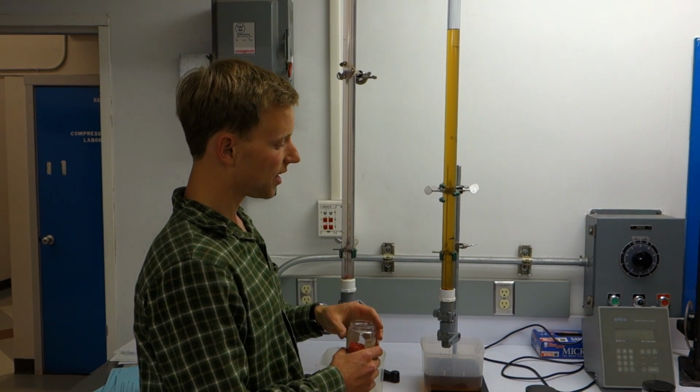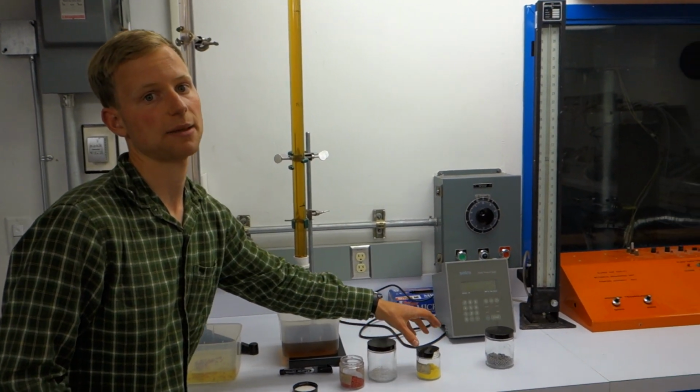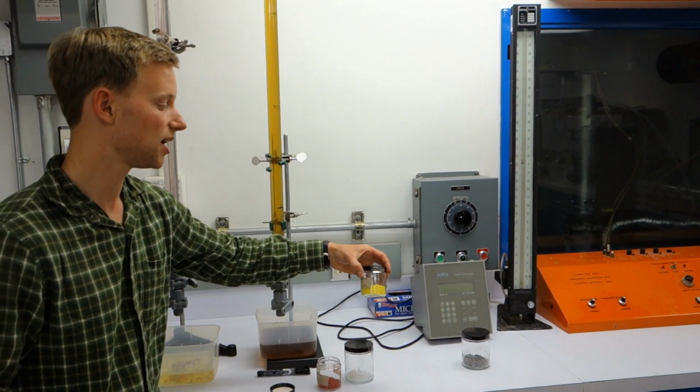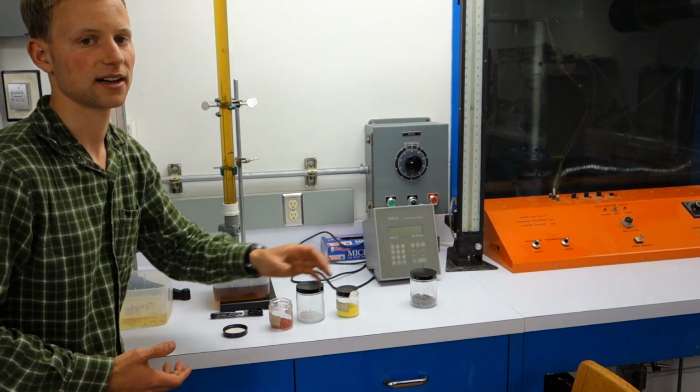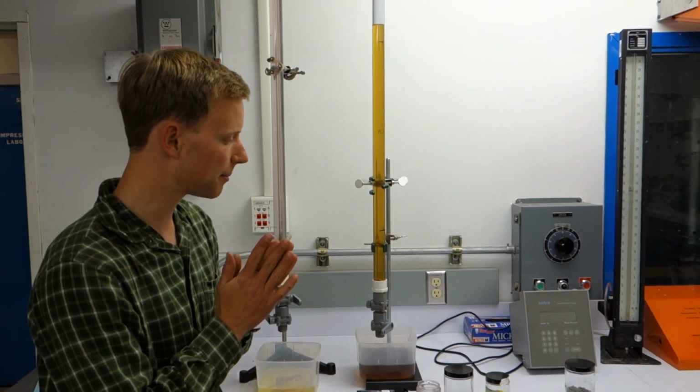and then solve for the viscosity of this liquid. And of course note that we have different spheres to be working with, and they should all give us the same answer for viscosity because we used Buckingham pi to find how the pi groups relate. This should be problem independent.